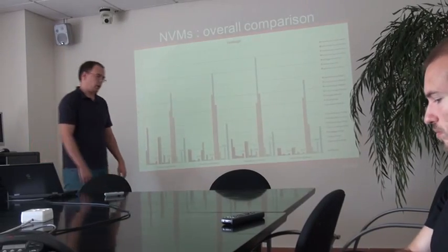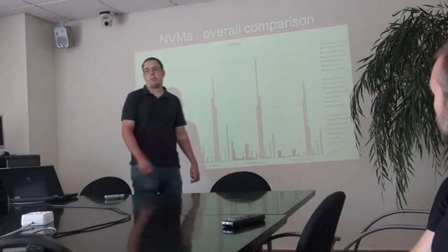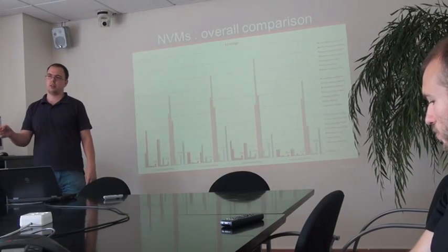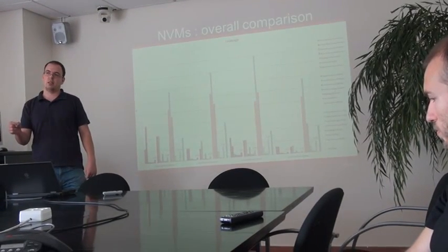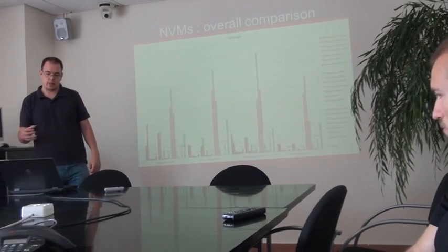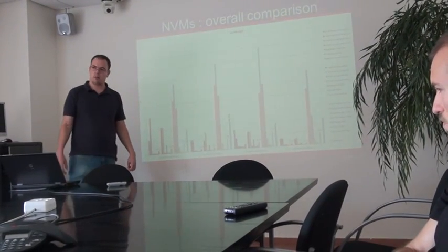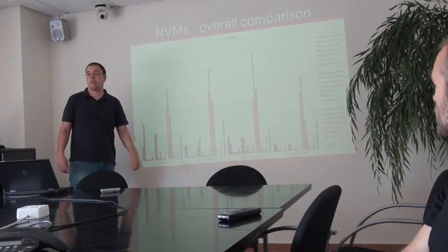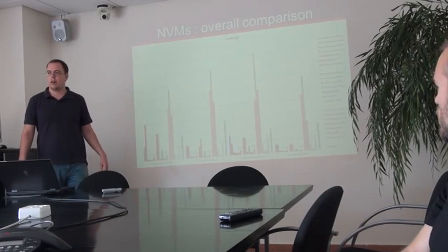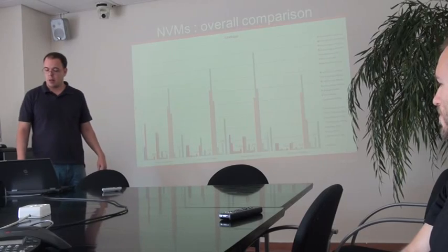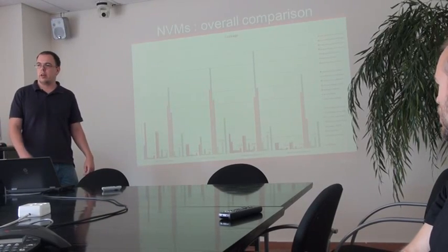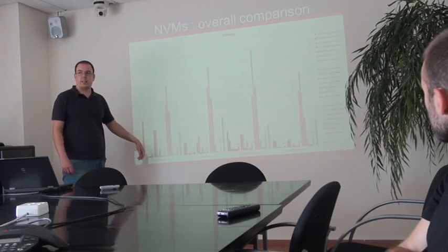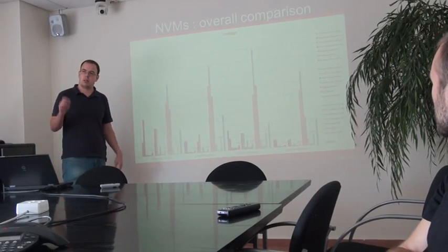Leakage. Okay, DRAM is a leaky technology per se. We have to refresh the RAM because the charge stored in the capacitor leaks through the access device. But these technologies are non-volatile, so we can gate off the current, and it doesn't lose the information. The only leakage appears on the external circuitry, right? But not in the cells per se.